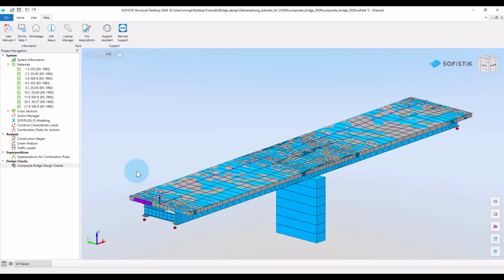To judge this, the typical load level on the bridge during the passage of the fatigue load model is relevant. According to Eurocode, this load level from so-called non-cyclic actions should typically be assumed to be the frequent combination of permanent loads, settlements, and temperature loads, combined to give the most unfavorable effect on the stress range.